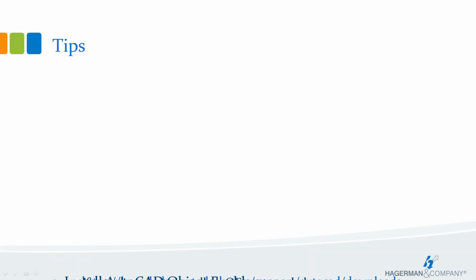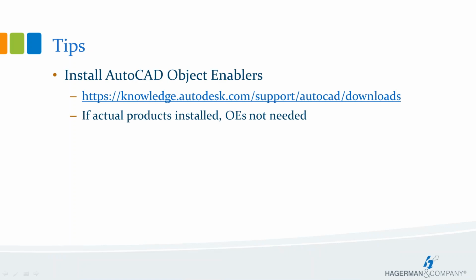So first and foremost, in order for Navisworks to digest and show all of the AutoCAD objects from all the different tool sets, like Plant 3D, Civil 3D, and so forth, you'll want to install all the available object enablers when you install Navisworks. That will ensure that all of the objects that are in those models will be visible in Navisworks.